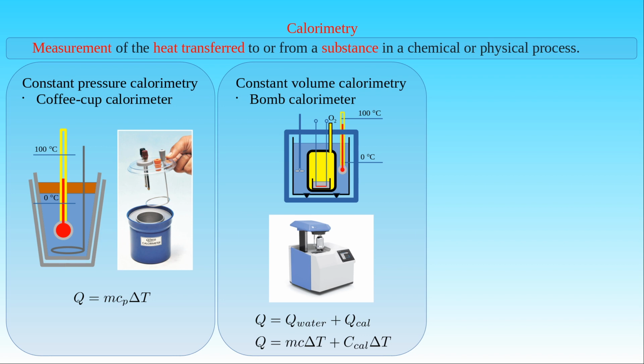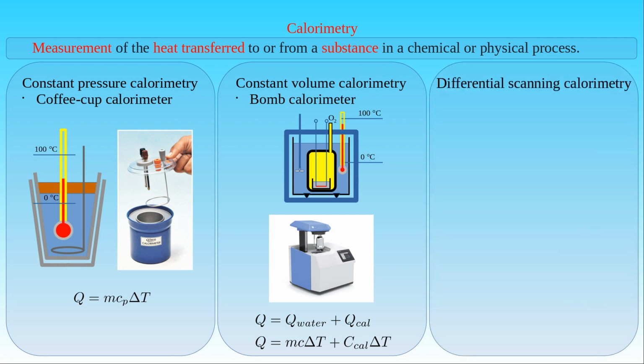The third approach presented here is called differential scanning calorimetry, which is used to study endothermic and exothermic transitions and determine transformation temperatures in glass transition, melting or crystallization. This technique also enables thermal property and purity analysis, the study of heat history in chemical reactions, and allows one to monitor the variation of the specific heat of materials as a function of temperature.